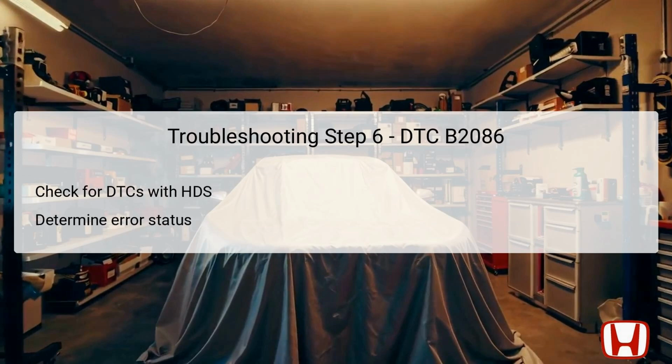It is essential to note that if the DTC reappears, further diagnosis is warranted to locate the specific failure point within the circuit or components. Continually checking the DTCs is a critical part of effective troubleshooting.